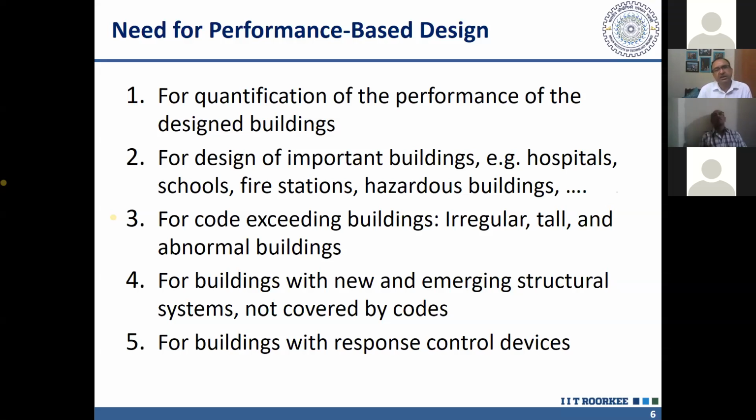And when we have buildings with response control devices, either in the form of base isolation or dampers, it is preferable because generally we design these buildings for better performance objectives. So in that case, we would like to perform the design using performance-based design. Although for these buildings, conventional methods based on simplified analysis are also available.